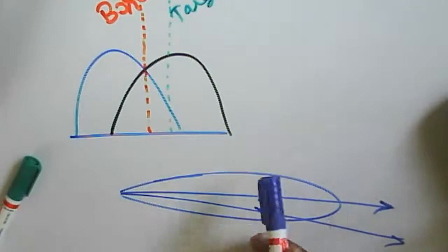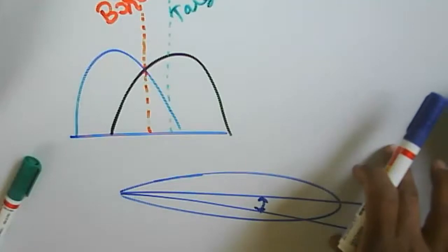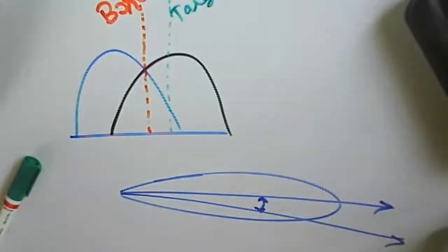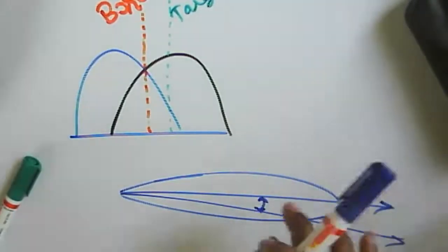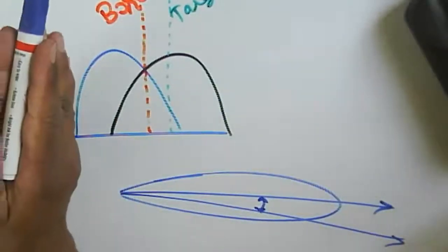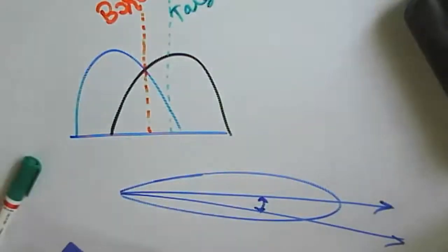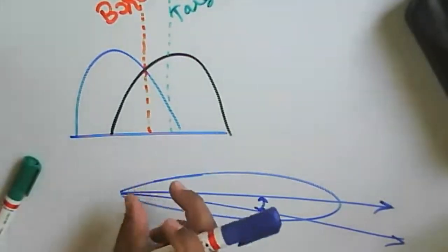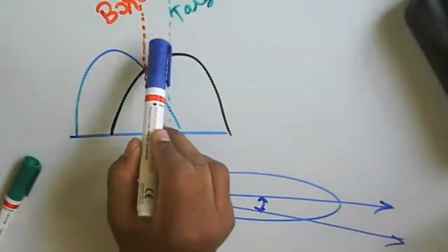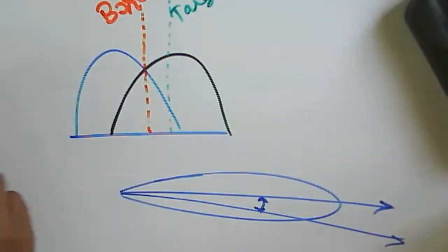Now in this case, what happened? This one is about a bore site, the bore site of an antenna. So what about the target and bore site? Because the target is in this direction, there is the antenna bore site. So we need to match the bore site as well as the target direction. Once the bore site and target direction match, we can identify the target, or we need to lock the given particular position here. In that case, the angle between this target and this particular bore site is to be zero. So we can locate a target easily.